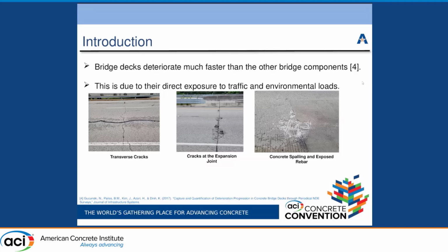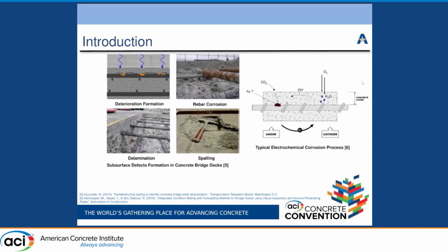As you can see, this is a picture of a bridge deck that we took. There are transverse cracks, cracks at the expansion joint, concrete spalling, and exposed rebar.